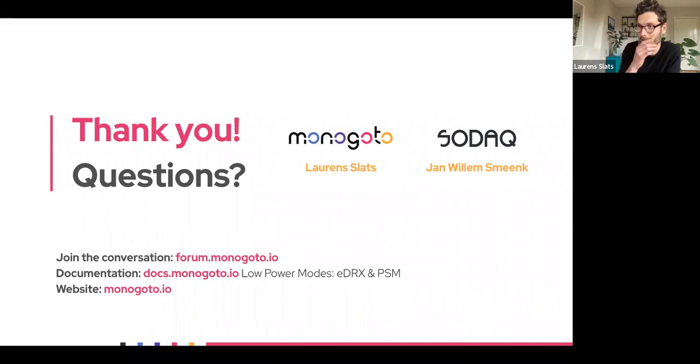So I see a first question from Sokulo. At PSM modes, can that be activated by sending an SMS to the device itself? Well, the beauty is you can. Okay, so there are two things you need to keep in mind. First, when a device is in PSM mode itself, then it cannot receive any messages or any data from the network. So a device in PSM mode cannot receive any SMS or text messages.